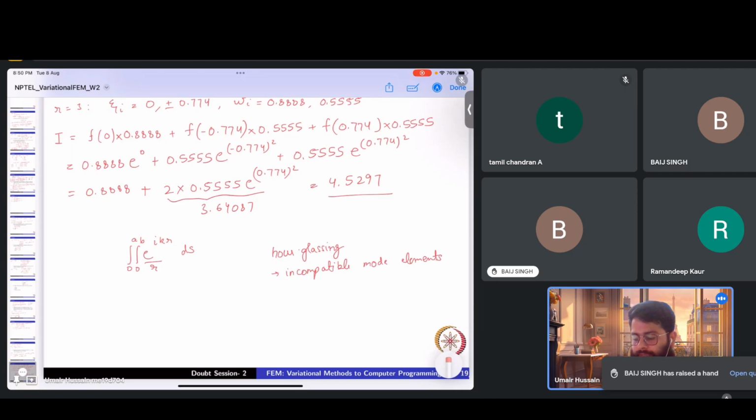But the deal.II libraries have very good classes and objects which support the solvers. There are very good functions there, so a lot of things can be automated, like imposing boundary conditions and assembling the local elemental equations into global equations. But it's very fundamental, like you have to write a solver from scratch. You have to write a proper C++ program for that. So it completely works on C++. Yes.